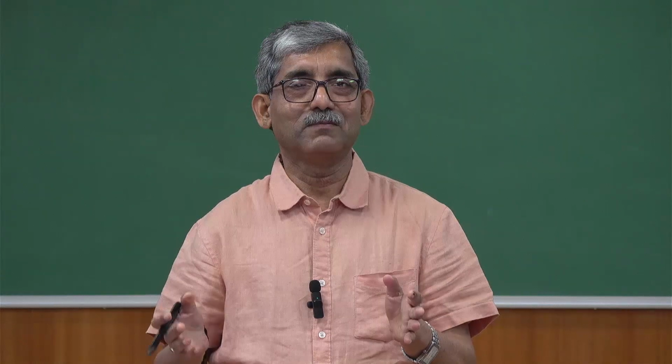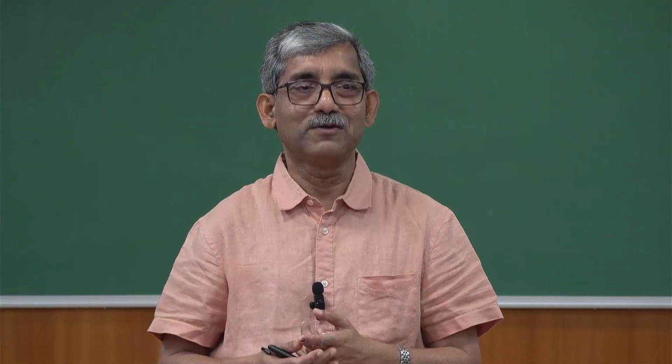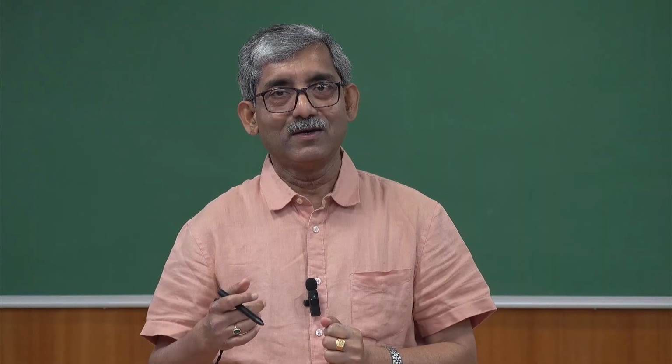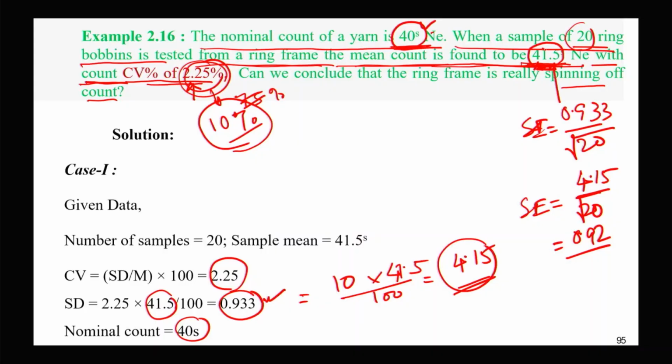This is basically a problem of interpretation. That's why we should not only concentrate on the mean value. We should concentrate on the standard variability. If the variability is very high, then the basic importance of the mean value is actually lower. We should not consider it a good quality product, although we are producing it within the significant range.